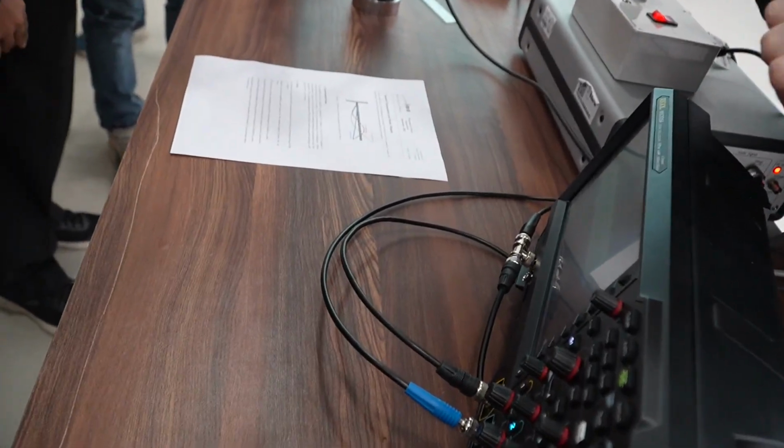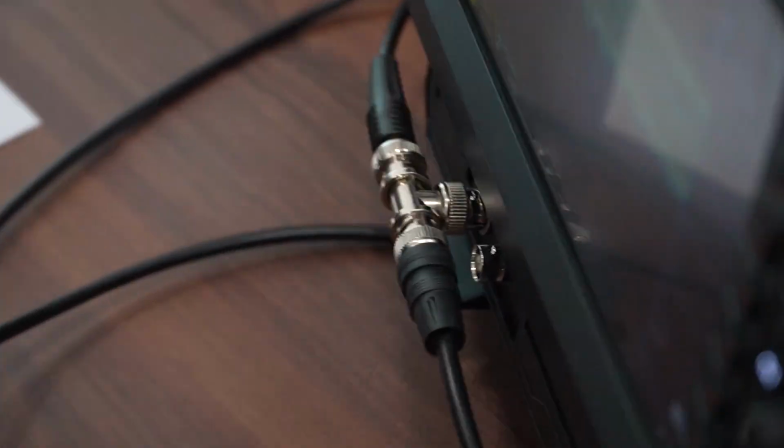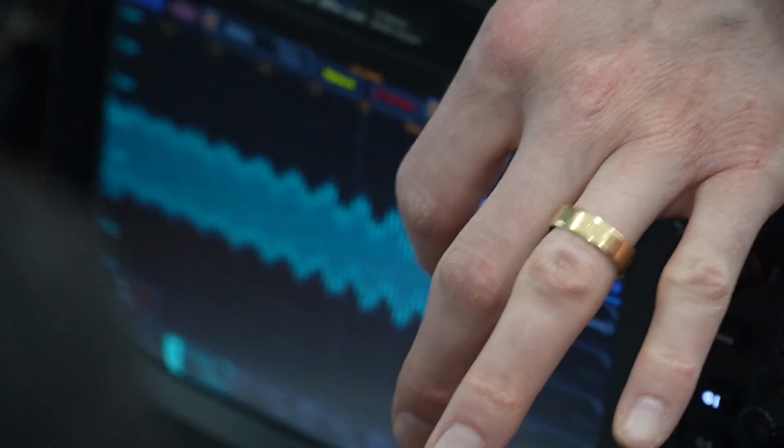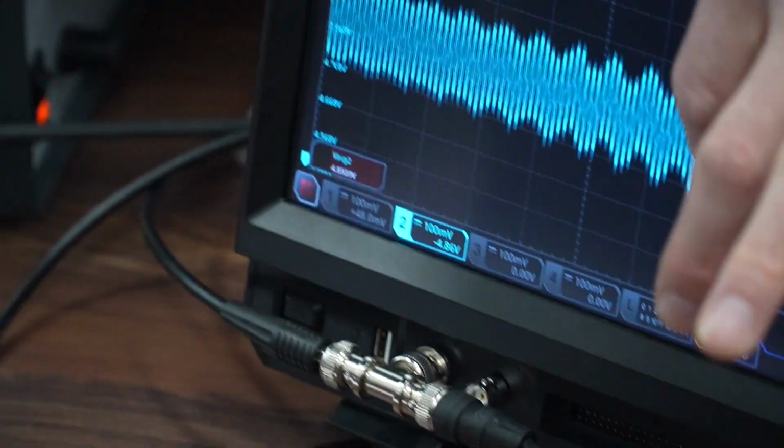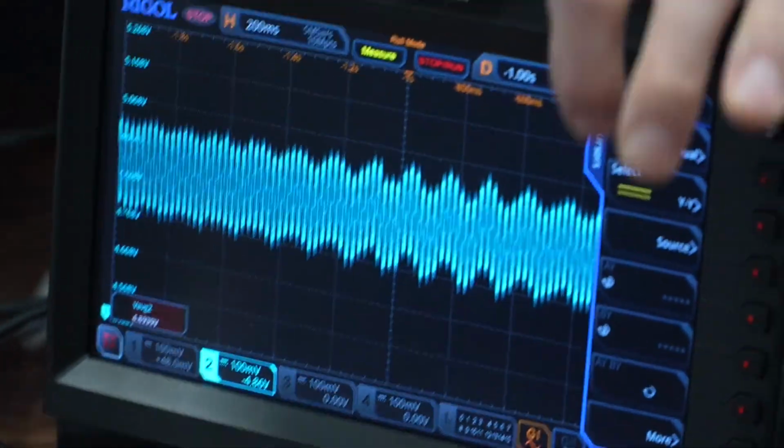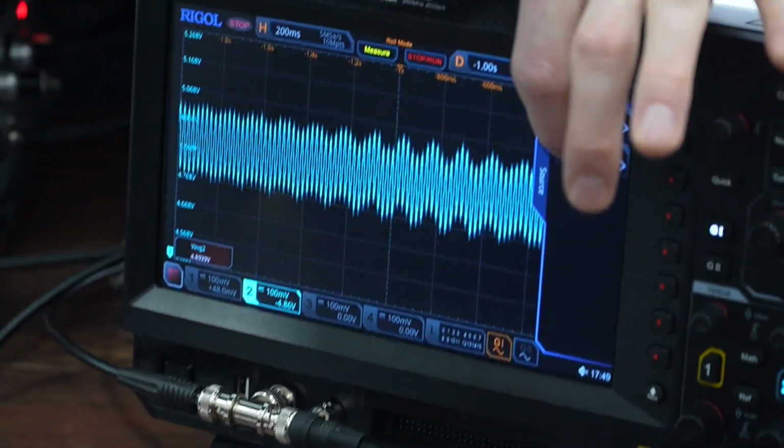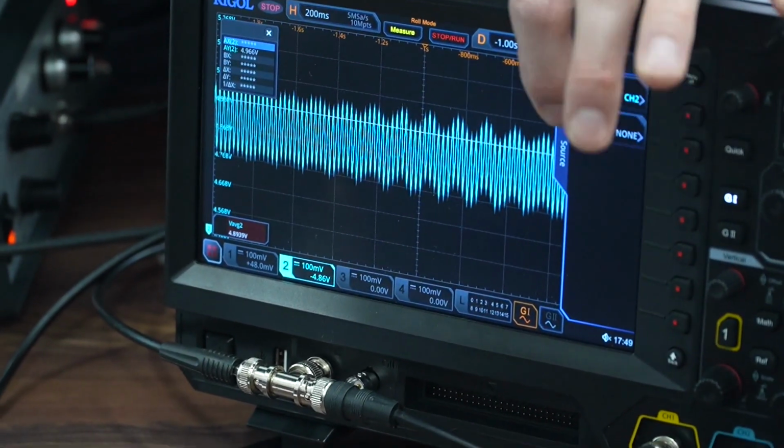I don't know why we have these two signals. We cannot really get rid of that. But you have a mean, right? You have the mean voltage of the blue signal. Let's turn down the function generator for a second. And now let's go to stop. Okay. And now let's go to cursor. And now let's go to manual. 4.96. Look. Okay. To a YY cursor. And now ideally, source A is channel 2, source B is channel 2.